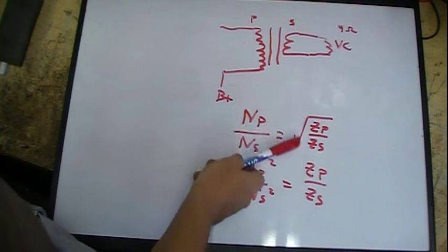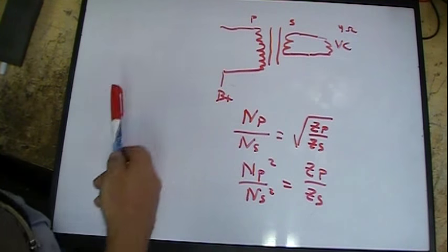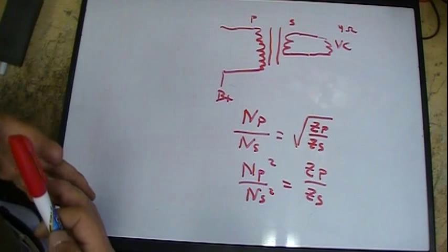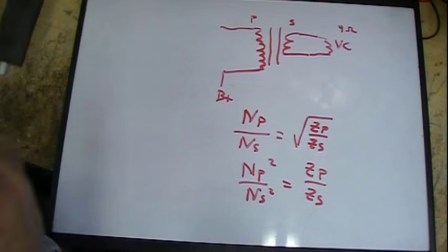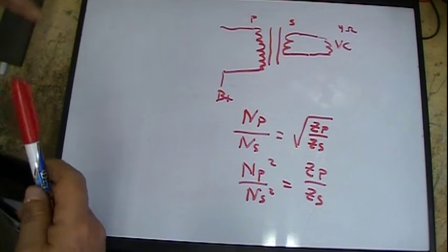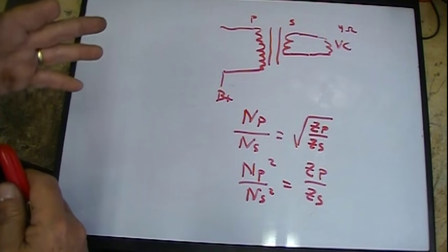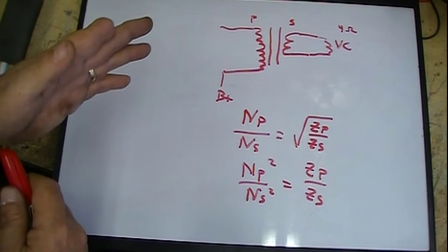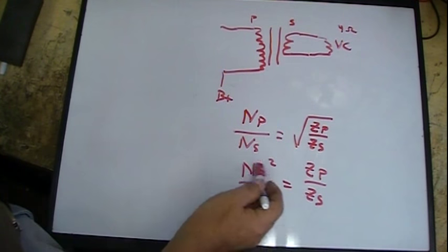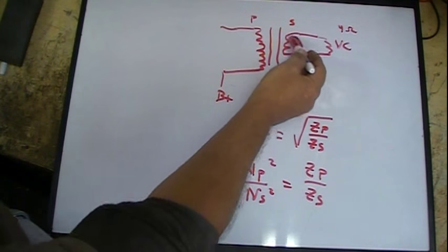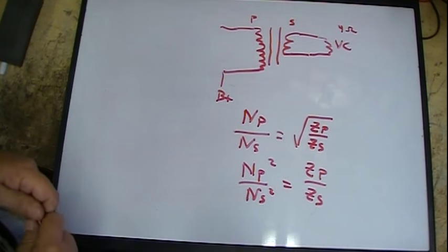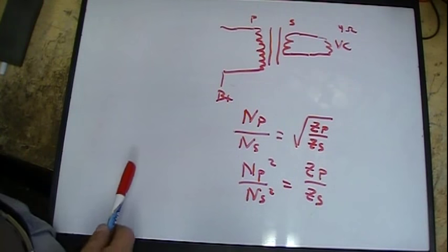But that's all it is. It just basically follows the formula, just same as everything else follows in here. Remember, impedance is just AC resistance, so it's just measured in ohms. So it follows Ohm's law. So basically the EMF, or the voltage, the signal voltage, equals the signal current times the impedance. So that's why it follows this turns ratio, because the voltage and current both follow that turns ratio. And there's nothing really magical here. That's just basically all it is.